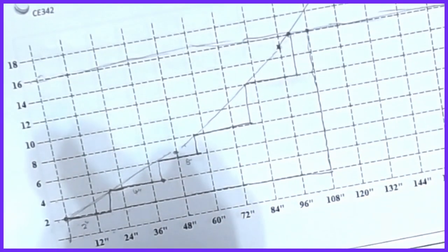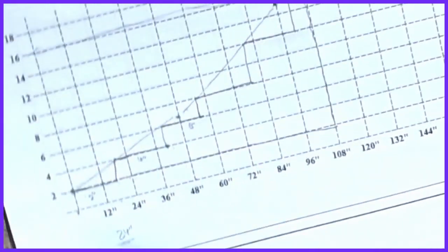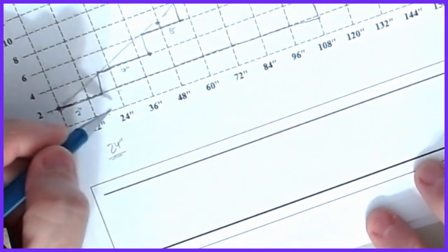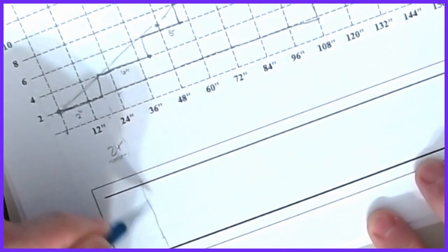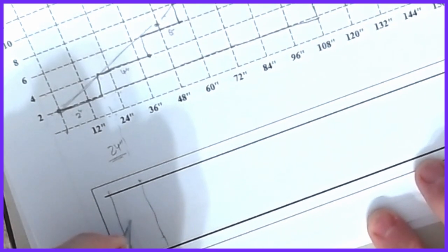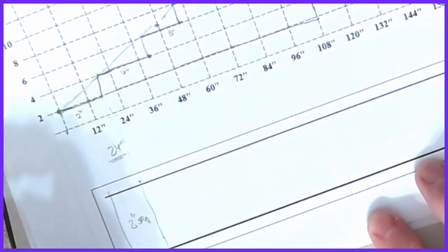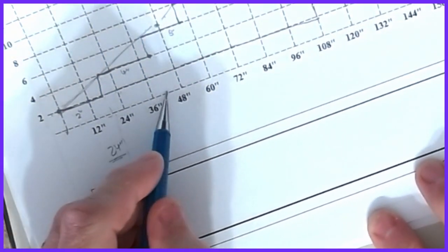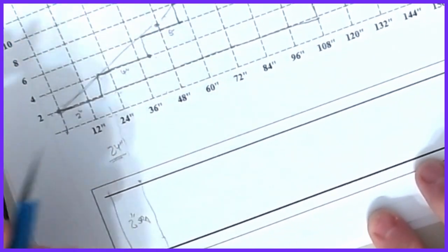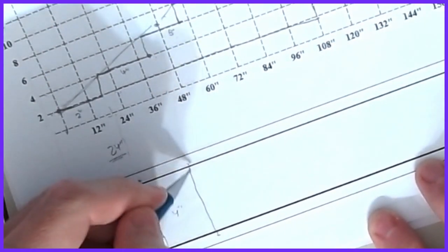So those rules of thumb that I showed you, keep that 24-inch special number in the back of your mind as you're looking to lay this thing out. Okay, once you have that, then you can come in and draw the bottom of this, and I can extend these lines down. So I know that in this region, if this was 18 inches, with a 2-inch spacing, you would need 9 of them there. So you can start getting a quantity check. And then from 18 to 40, at 4 inches, I probably need 6 more at 4-inch spacing to get me out to here. And that's the way that you start to lay this thing out.